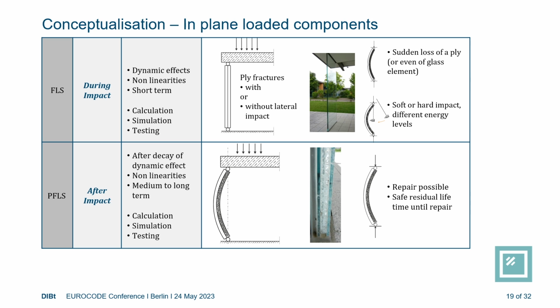For in-plane load components, that's more or less the same, but with increased requirements, because normally the in-plane components are part of the overall structure, and we have to care that after the impact or after the breakage of a ply, the overall stability is not affected. And therefore, we have to care that we account for dynamical effects, that we have residual capacity with a broken ply, that repair is possible, that the safe residual lifetime under repair is given, and so on.